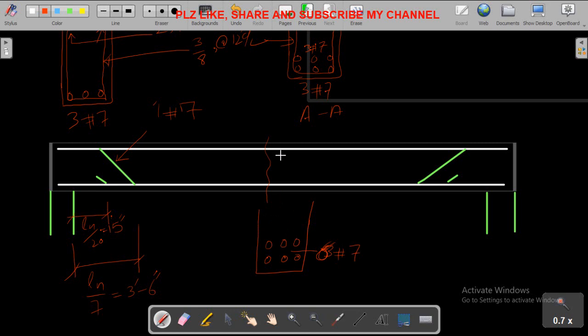And again we have stirrup, which is continuous, this is number 3 at the rate of 12 inch center to center, and at the top we have 2 number 4 bar to hold these stirrups, and we have 12 inch bearing, which will be a column, right?